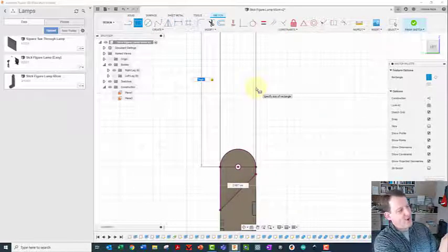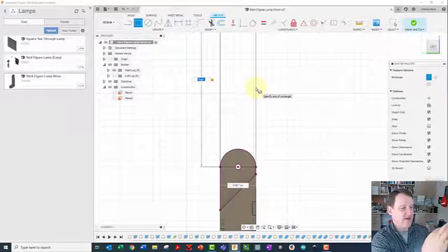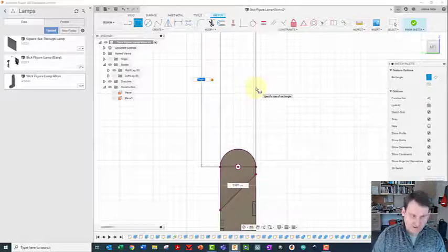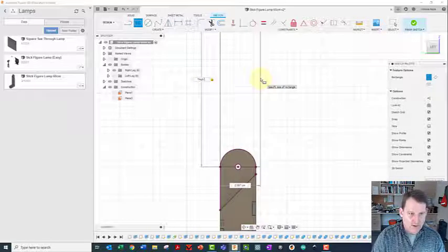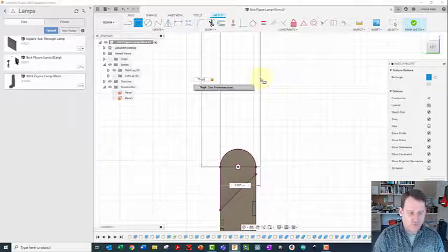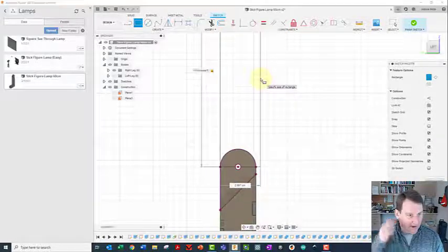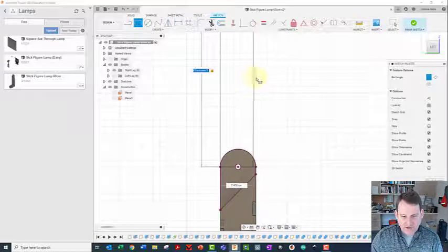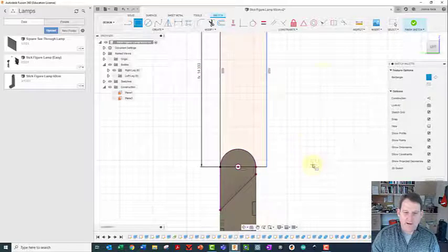So we actually need to go up to the rest of the height on the outside, which is 5 thicknesses higher. So this whole thing is 10. We're halfway up there. We want 5 more. So on the thigh, I'm just going to do thigh plus thickness times 5. So that should get me right to the top of it. And I'm not going to try and line up this right side because I'm going to do it with a constraint later.